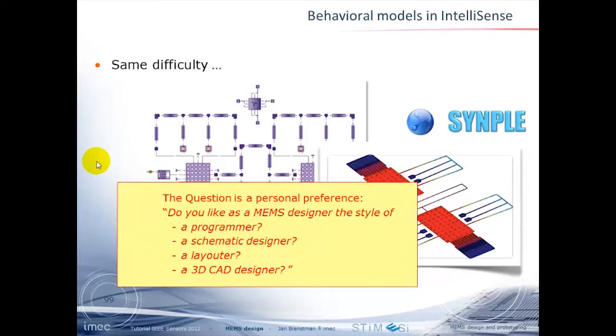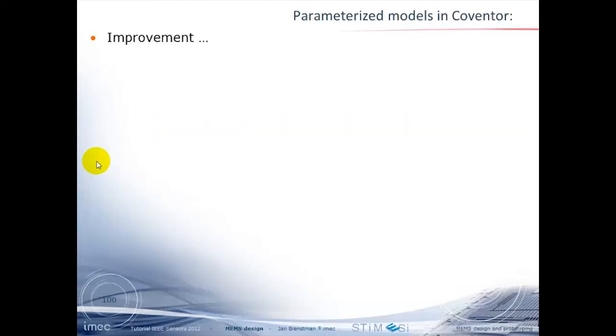Some people doing MEMS design prefer the style of a programmer or a schematic designer or layouter. It really depends on what you are skilled at and what you want to model. Because this approach is more tailored for lumped devices, and typically these mechanical SOI type of devices. But I think you are getting into problems if you have a bulk micromachined device.